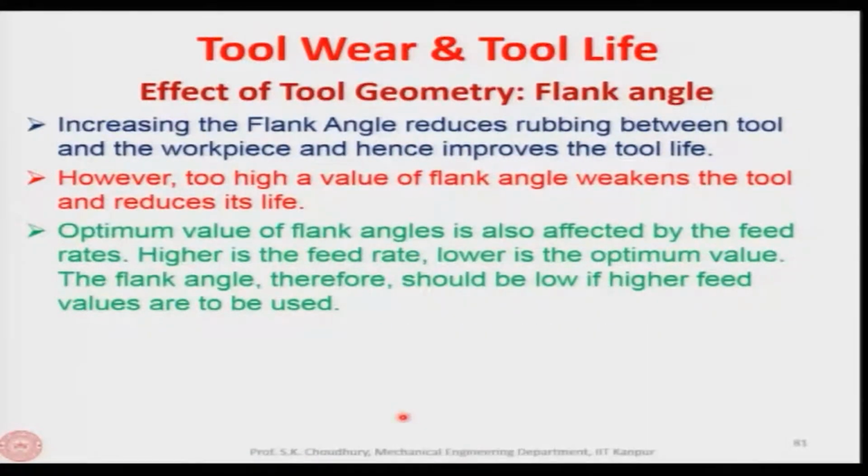Now, the flank angle. Increasing the flank angle reduces rubbing between the tool and the workpiece, and hence it improves the tool life. But while increasing the flank angle, as we have discussed earlier also, the cutting angle reduces and the tool again weakens, which reduces the tool life. The optimum value of the flank angle is also affected by the feed rate. Higher is the feed rate, lower is the optimum value of the flank angle. The flank angle, therefore, should be low if higher feed values are used. So, these are the recommendations which are theoretically as well as experimentally obtained.